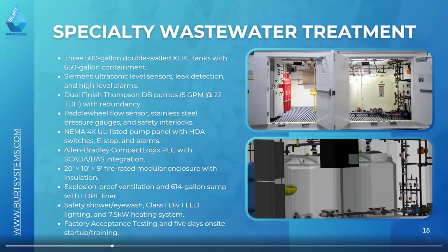At that point, pH adjustment essentially becomes a form of chemical injection system. So this is a fully containerized design. Not all these systems are skidded, as you might expect, like a pre-package. A lot of them are more of a modular or containerized design. This shows that you're doing that recirculation, that chemical injection, and all that monitoring, but you're doing it for essentially an off-site tank design.